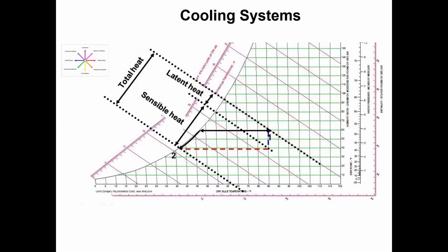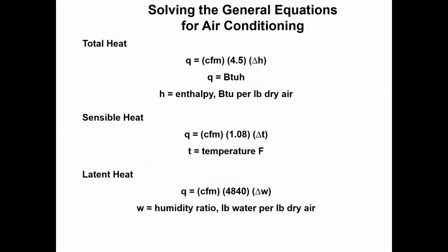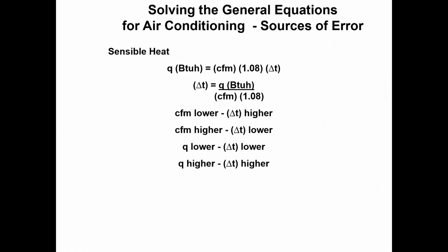This is a heating system. This is a cooling system. What's the latent heat, what's the sensible heat. Just get a good quality psychrometric chart, and we will go through the different questions and then the formula. If you go for this one, there's a total heat, then the sensible heat, and then the latent heat. Just simply go through all these ones, and I think you are quite familiar with heat transfer. These are all similar equations. These are not new equations which you haven't read before.